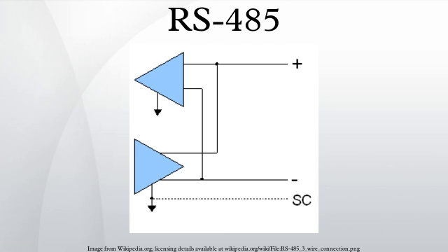To avoid these confusions, some equipment manufacturers have created a third D+ and D- naming convention. The standard does not discuss cable shielding, but makes some recommendations on preferred methods of interconnecting the signal reference common and equipment case grounds. Waveform example: the diagram below shows potentials of the plus and minus pins of an RS-485 line during transmission of 1 byte of data using an asynchronous start-stop method.